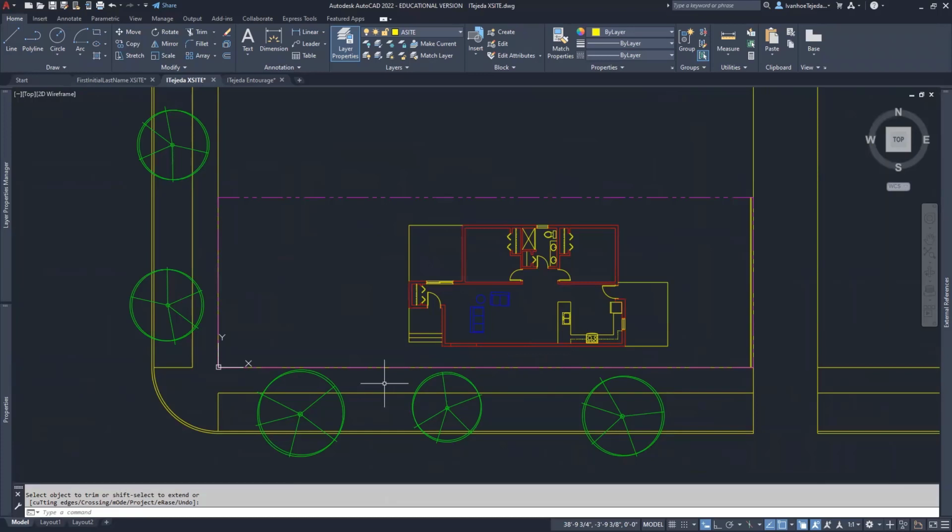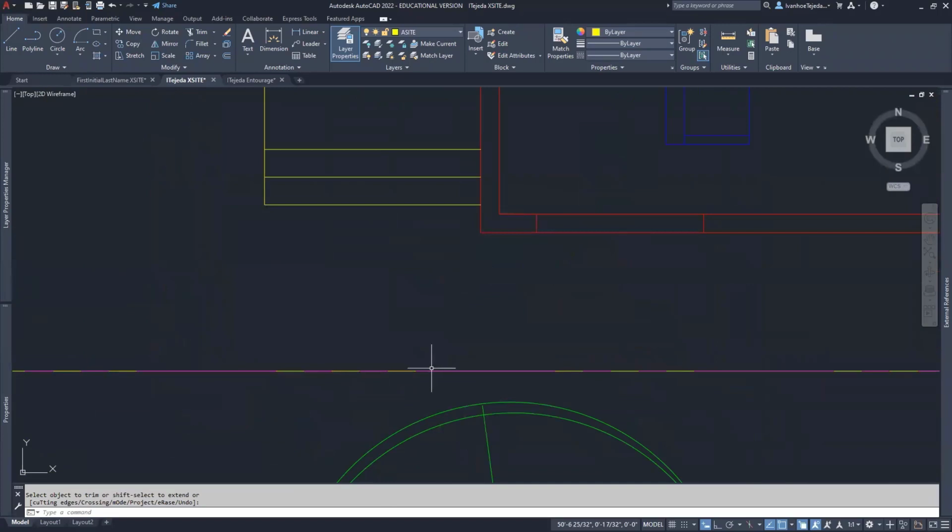So in my example, the way I put the stairs, I would then draw a line. It's on this XSite layer, and I draw a line. So I type L, enter, from this point here, and I bring it straight down. Perpendicular is fine. I click on it and enter, and then repeat the line command by simply entering. Pick this endpoint, take it down, let it go perpendicular like that, and then enter.